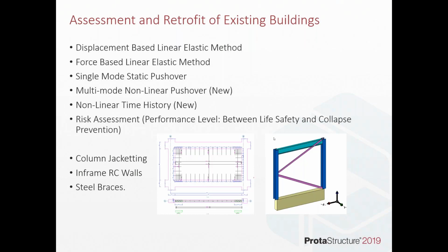If you are looking at upgrading an existing building, then you can take advantage of what I showed earlier with employing things like infill RC shear walls and column jacketing to help you strengthen the building to maybe meet life safety stages.